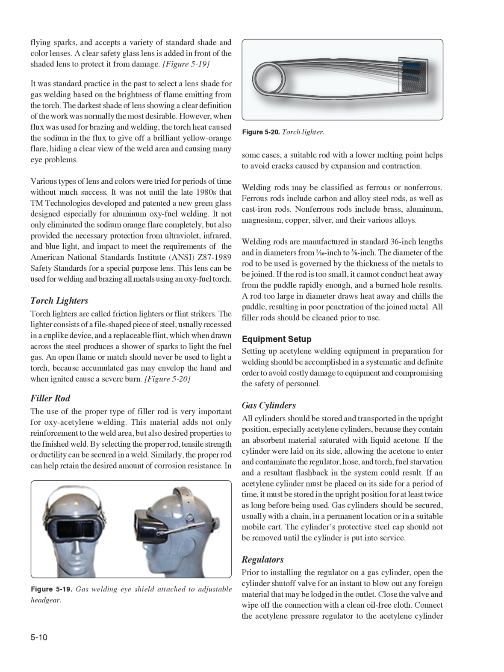If the cylinder were laid on its side, allowing the acetone to enter and contaminate the regulator, hose, and torch, fuel starvation and a resultant flashback in the system could result. If an acetylene cylinder must be placed on its side for a period of time, it must be stored in the upright position for at least twice as long before being used.